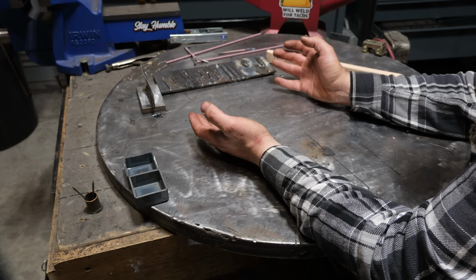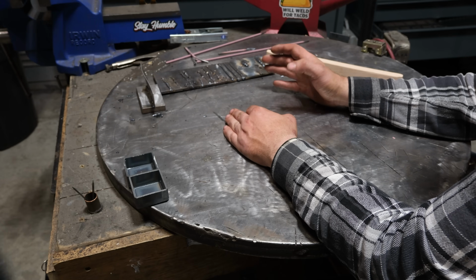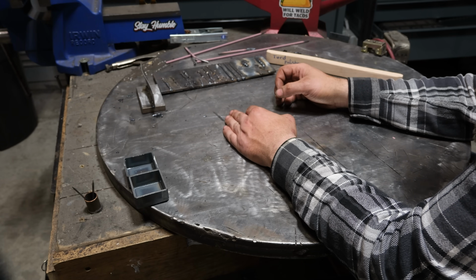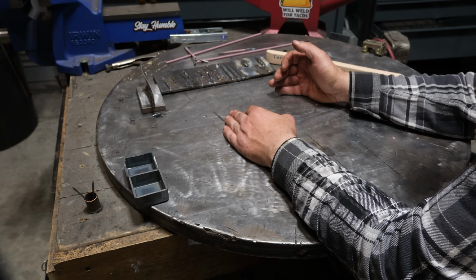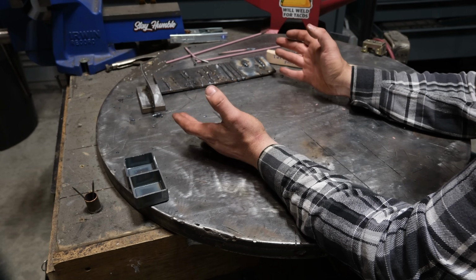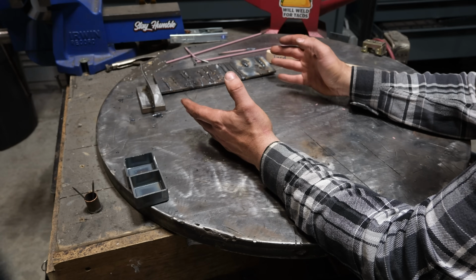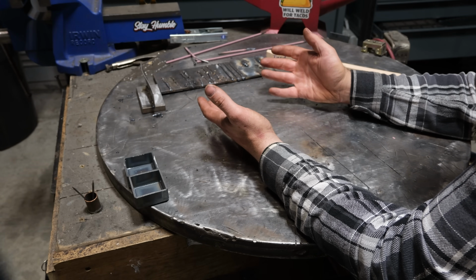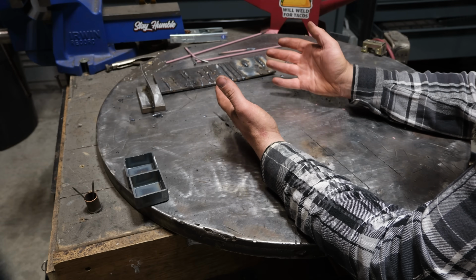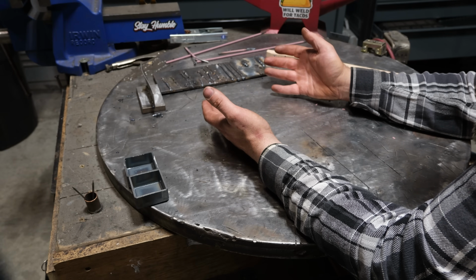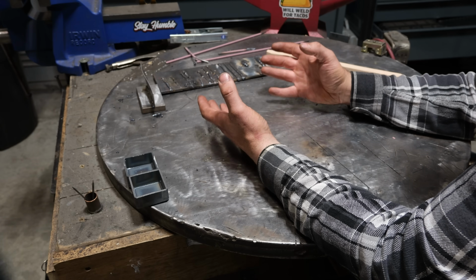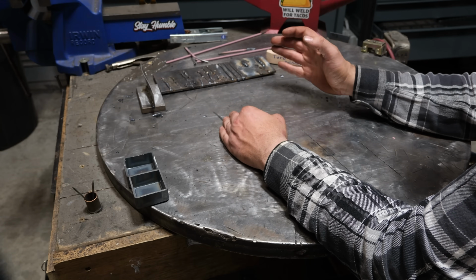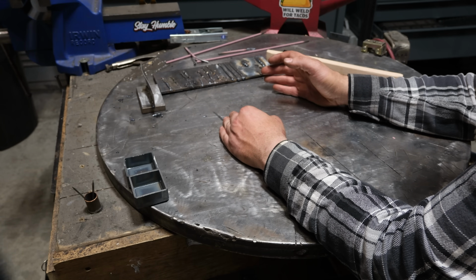But guess what? None of us are perfect and defects happen. And that is why it's imperative that you understand what the discontinuity is. Is it a defect? Is it bad enough to where it's going to compromise the structural integrity of what you're welding? Let's face it, if it's an ugly weld full of things that are likely places for cracks to propagate or just has issues, should you go back and grind it out and fix it? Absolutely, yes, you should.